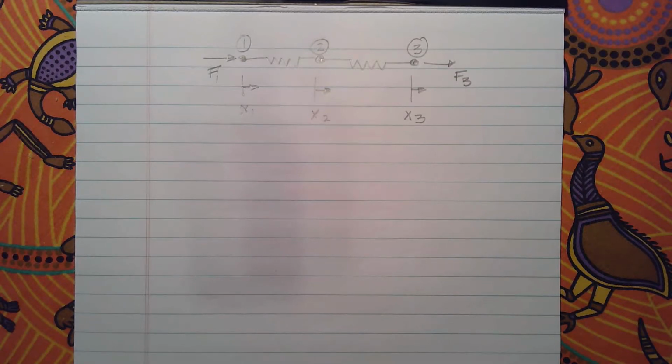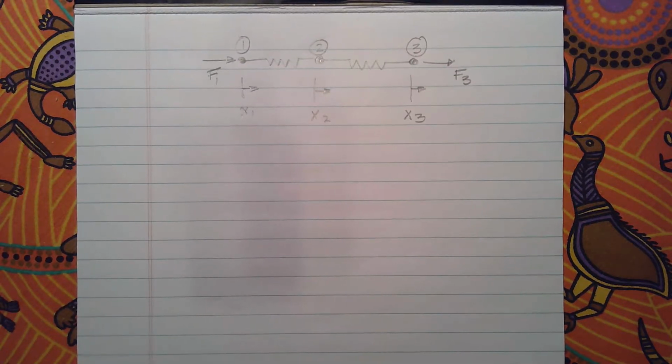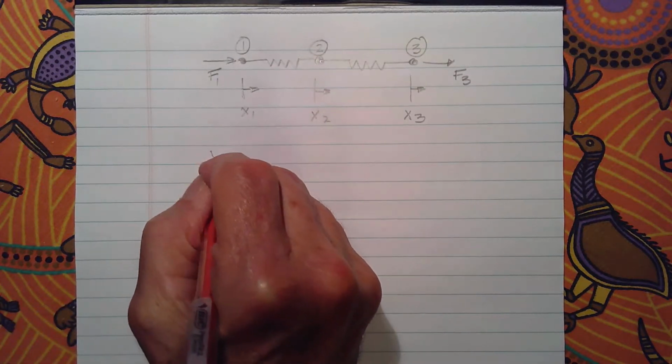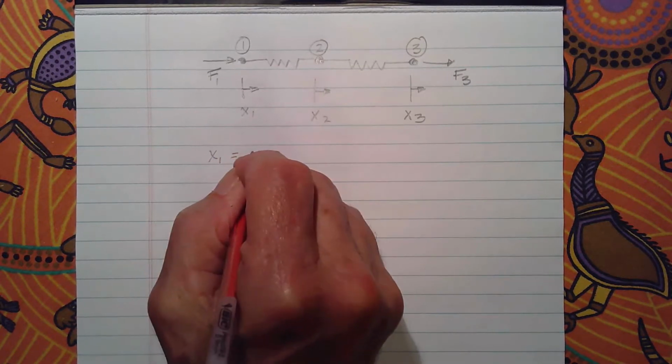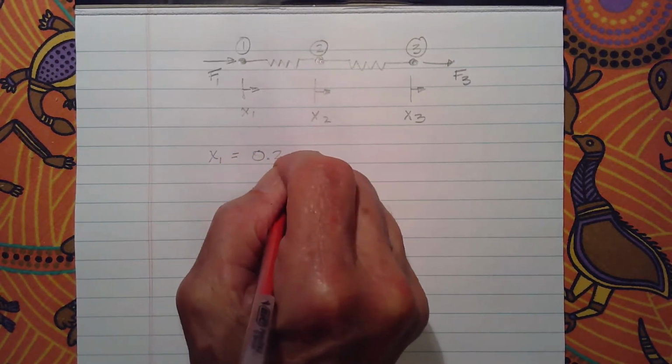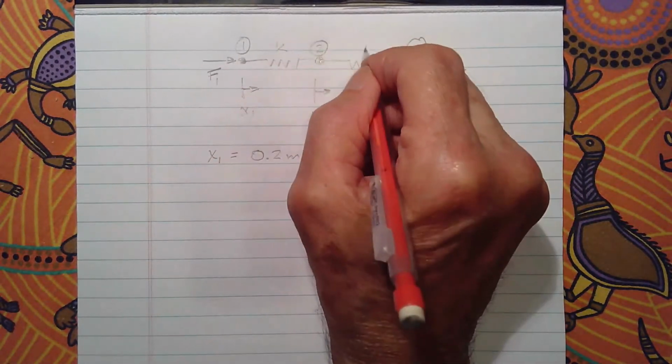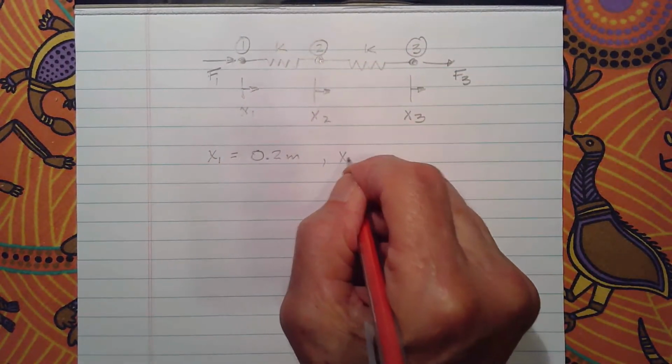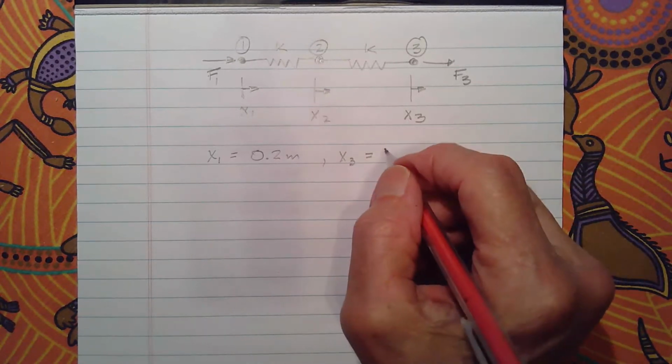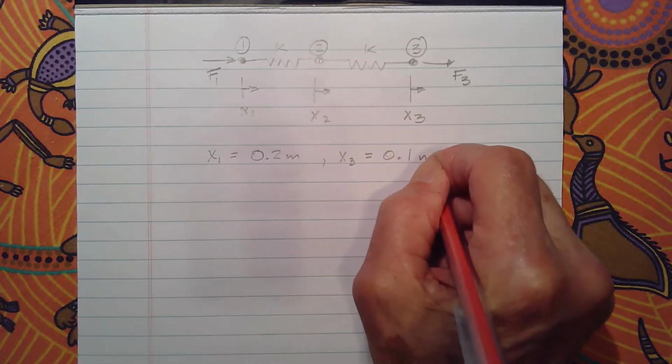As we saw before with the single element, whether you have the springs in tension or compression, you get the same expression. So that relationship that we worked out is valid whether these springs are in tension or compression. Let's work the first problem that we had before. We will give our nodal displacements, and x1 will be 0.2 meters. These are the same k's that we had before. X3, not x2, x3 will be 0.1 meters.